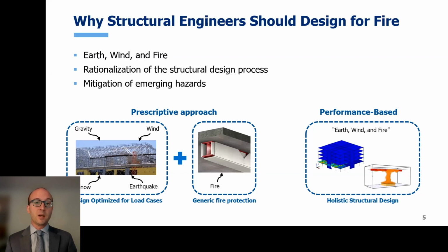In what we call a performance-based design, the design seeks to achieve a required performance, and the engineers must demonstrate that the design achieves this performance, instead of adopting a set of prescriptive rules that are deemed to satisfy. A performance-based approach is also the only solution when there are no prescriptive provisions, for example, because there is no collective experience from the profession with new systems or innovation.